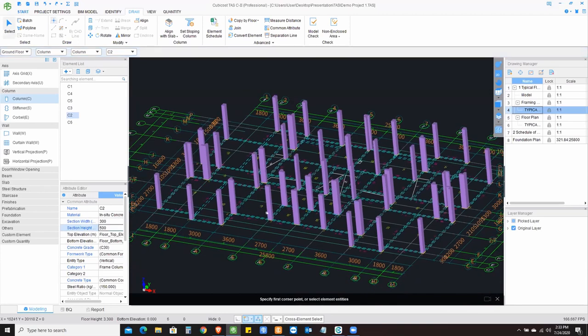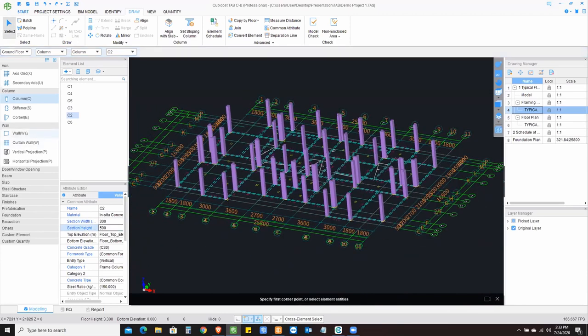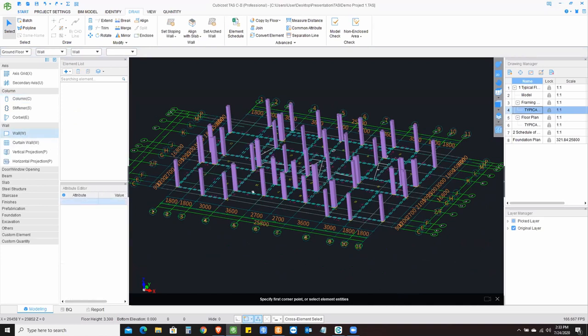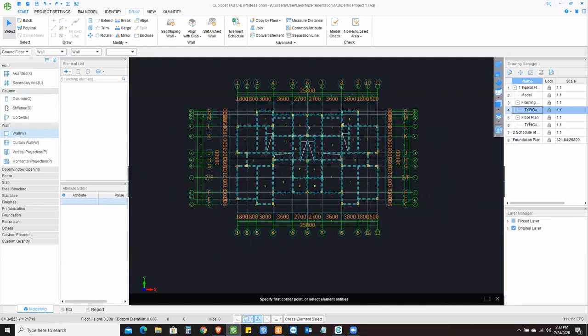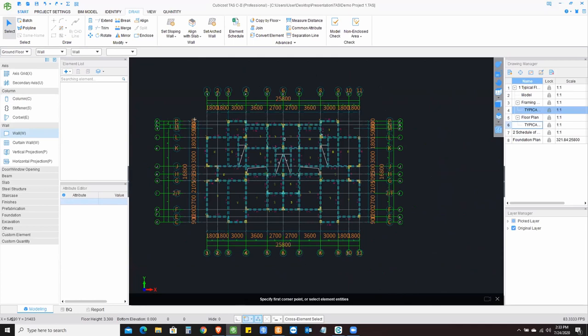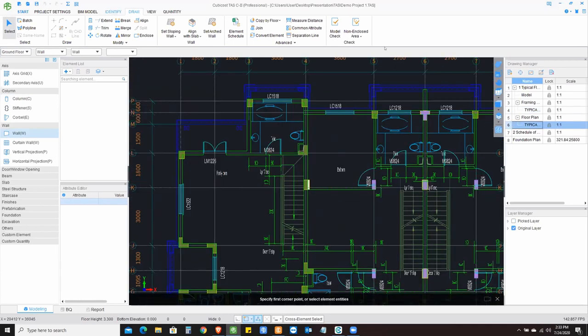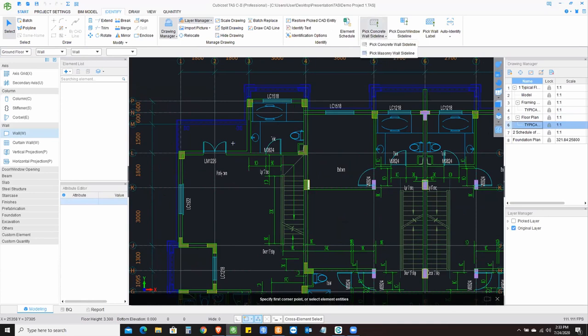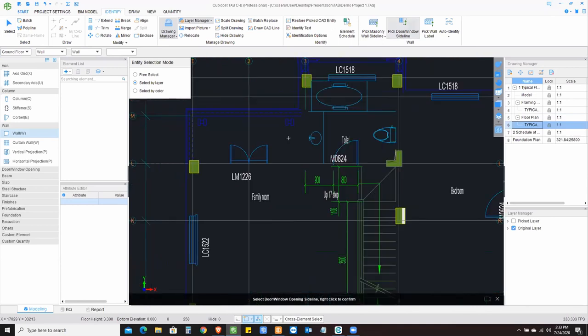That's basically the introduction of one element, but we will proceed with other elements without much detail because all the steps are similar. So I'm going to go ahead and choose wall. For wall, I need to then go to a floor plan or an architectural plan. So I've got an architectural plan here for this building. 3 simple steps again. So I'm going to pick up the sideline of wall, right click for confirmation. I'm going to let the software know, okay, there's a window or door opening coming up here. So consider that as well.